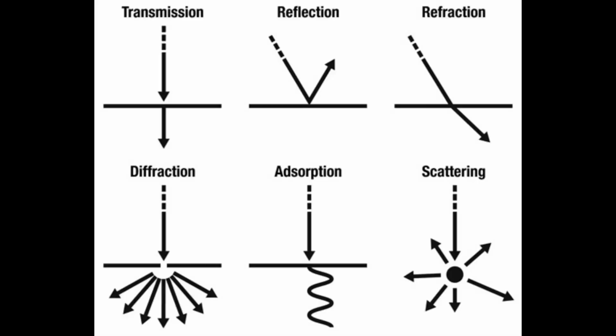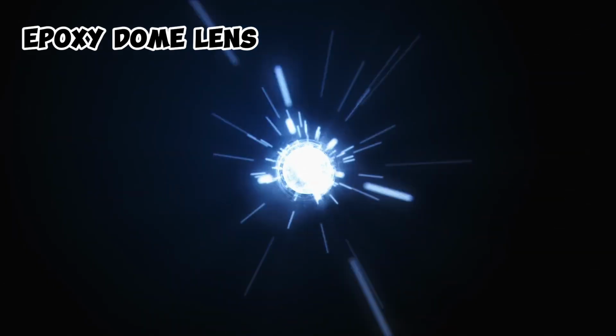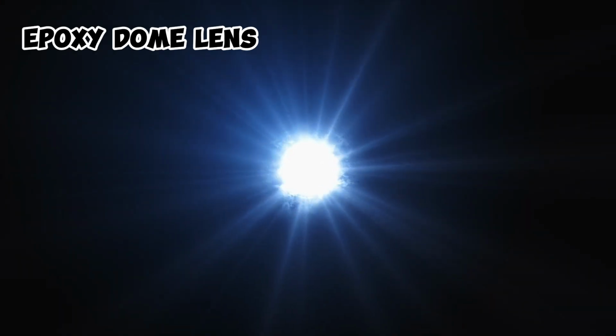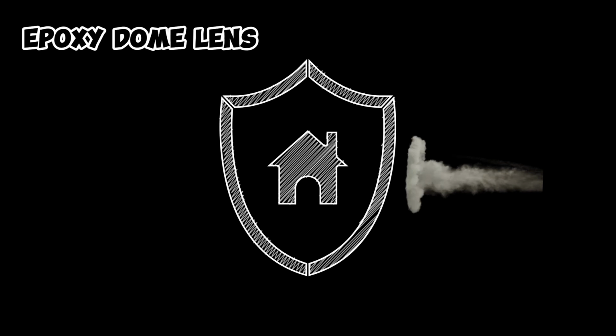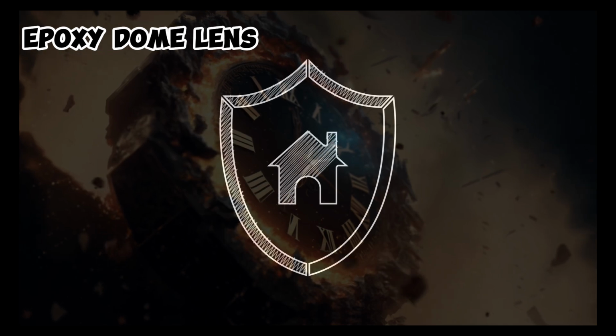Light transmission. It allows most of the light generated by the semiconductor to escape the LED package. Light focusing. It shapes the light beam, determining the viewing angle of the LED. This can be narrow for focused applications or wide for broader illumination. Protection. It acts as a protective barrier, shielding the delicate semiconductor from external elements like dust, moisture, and physical damage.